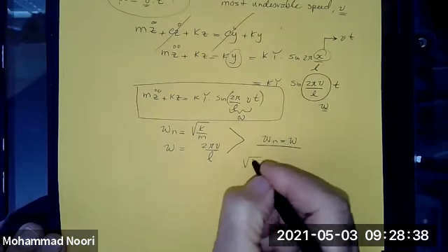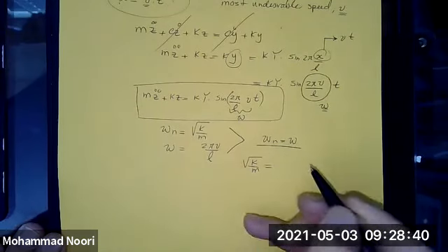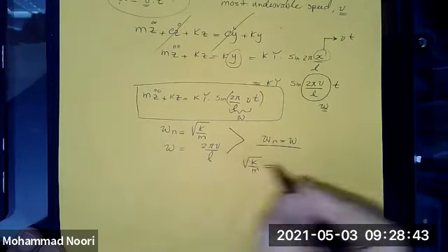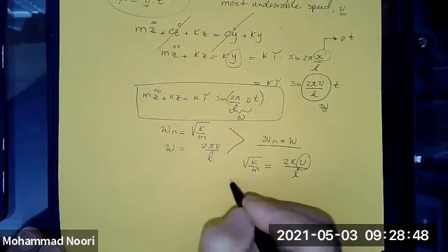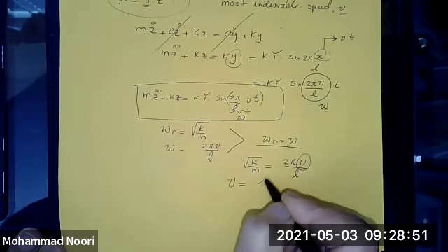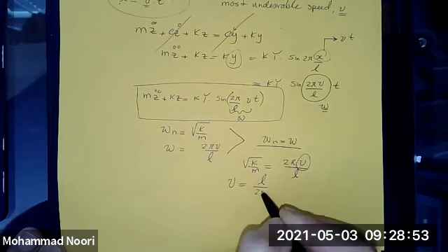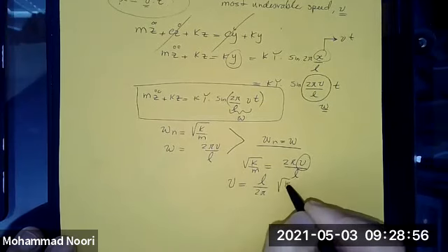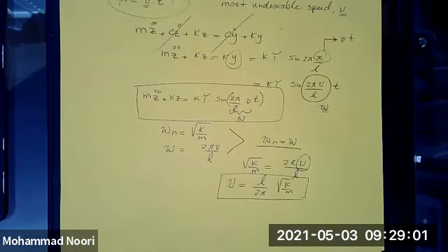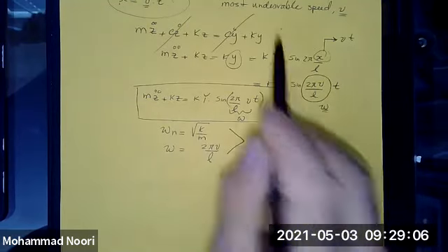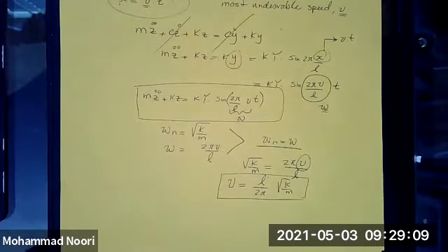So let's just equate those two, which, of course, given that this is a function of that velocity, we can find that velocity to be L over 2 pi times square root of k over m. So the velocity that we should avoid is simply related to the length of one cycle of this road's roughness divided by 2 pi times the natural frequency of the system.